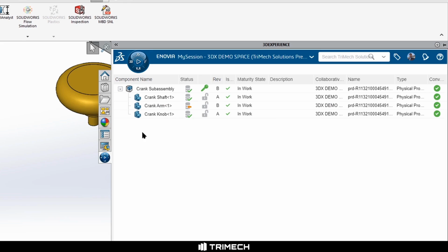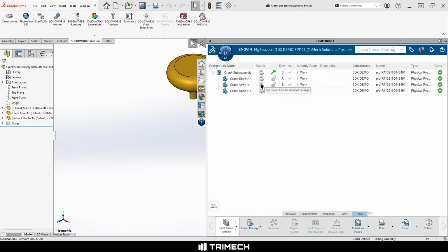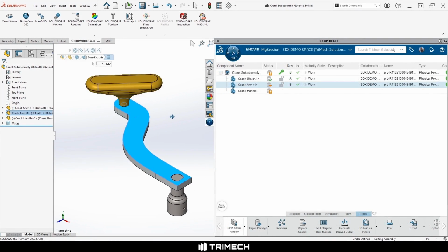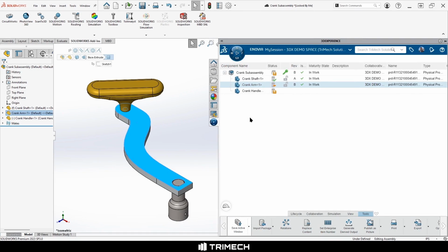To minimize the possibility of mismatches, be sure to clear your local cache before trying to integrate a CAD package back into your file set. To reintegrate the modified files back into our tenant, we need only to save them with our 3D Experience add-in. During the packaging process, the files retain their platform file identity and are seen as modified versions of the existing files.